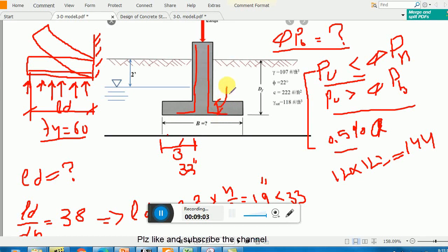Okay, so this length is basically called the development length in compression. This is denoted by Ldc. Remember, this hook length is not included in the Ldc. Remember, ACI basically defines that this hook has no role in compression splices. Remember, this is very important. But if this development length is not satisfied, then we either increase the depth, the thickness of the footing, or we provide this hook. Okay, they work a little bit.